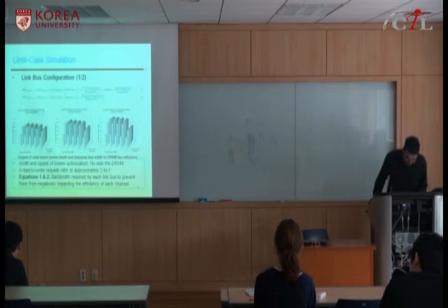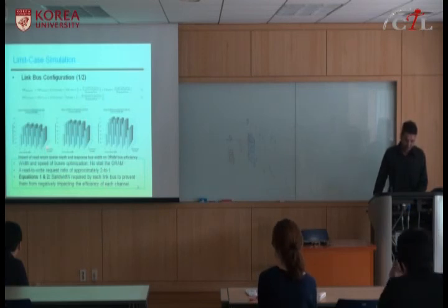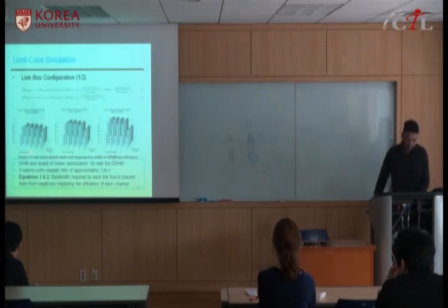That means the response link should be more than this: this is 24, maybe this is 16, 12, 8, 4. So the response bus width should be at least 8 bits wide, and the request link can be anything, like 4 or 24.